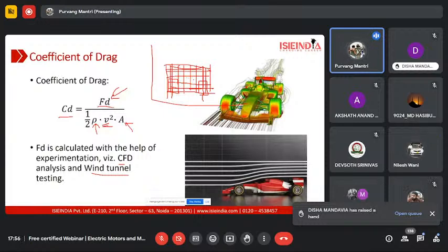And if you want, you can increase that number by a decimal point or something, because I have told you to just calculate how many blocks are entirely covered by the vehicle. If they are partially covered, and if you're neglecting it, it's all right. If they are 50% covered, then count them as 0.5. Okay, and that's how you get frontal area. This is like the basic grid method. But the actual method which I would recommend to use is the area under the curve method, which is nothing but your integration.